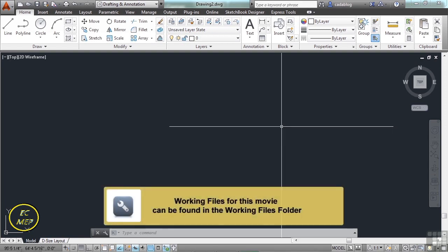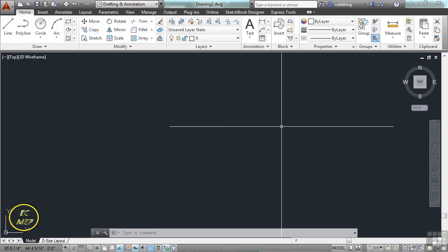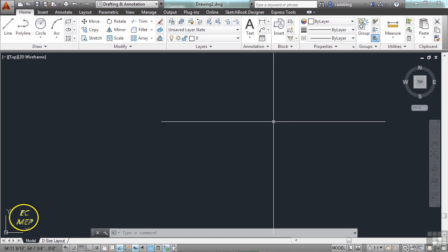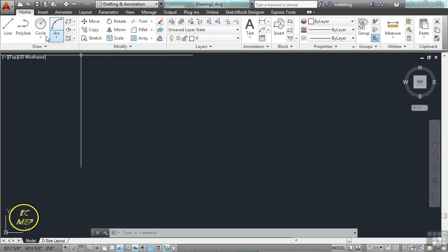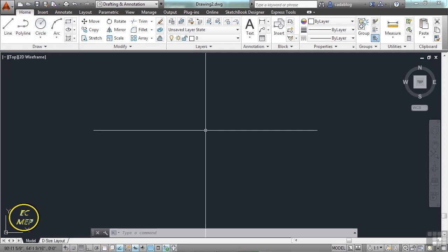You can draw lines and polylines now, and now you're going to need to know how to draw circles. Circles are used for many things: holes, different designs, wheels, gears. I can go on, but you get the idea. A circle is very simple. In geometry, it is defined as all of the points that are equally distant from a single point. To draw a circle in AutoCAD, use the circle command. Just type circle on the command line, or just the letter C for the command alias, or click on it up here in the Draw panel on the Home tab in the ribbon.